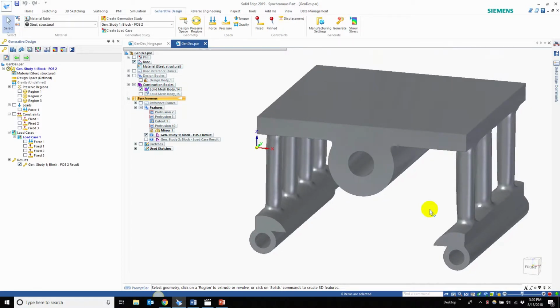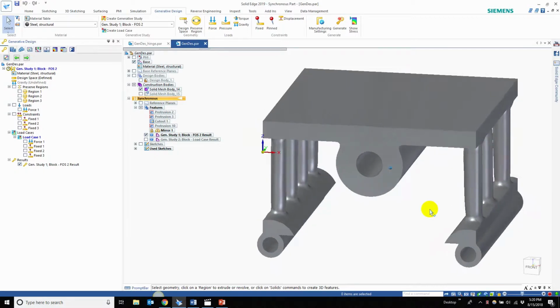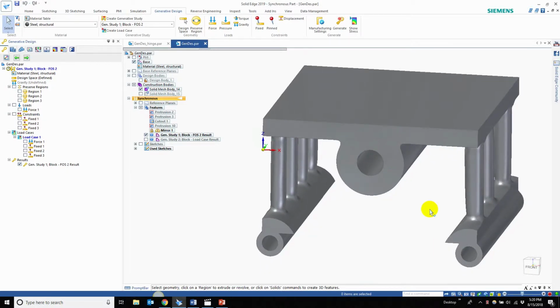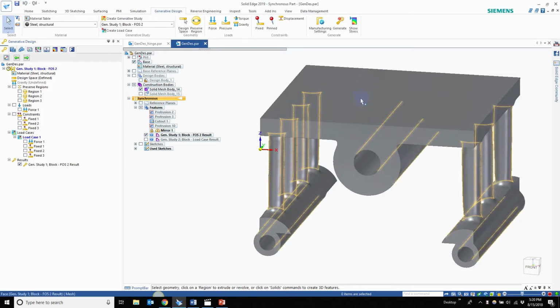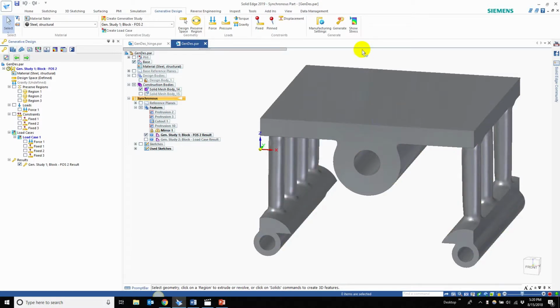And if I haven't said this before, definitely with a factor of safety, it does work better with a longer study quality. So this one was run for about 10 minutes, but factor of safety will take a longer study than the previous ones with just mass reduction. And that's just with my knowledge after going through these models.